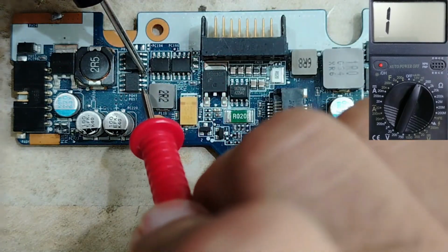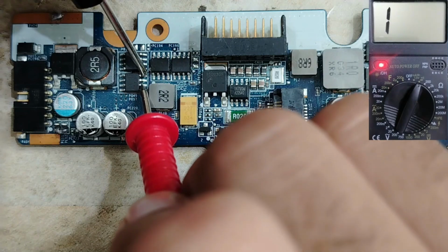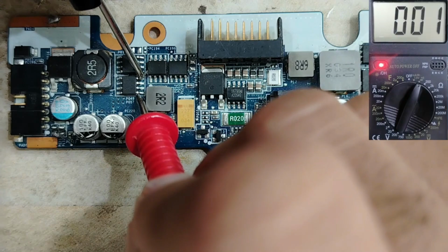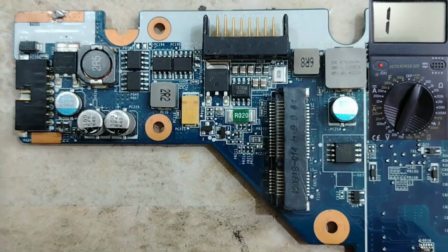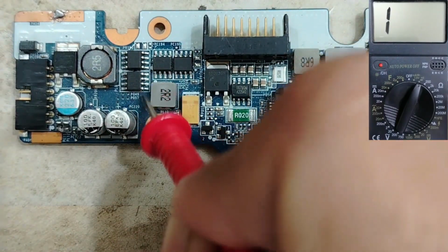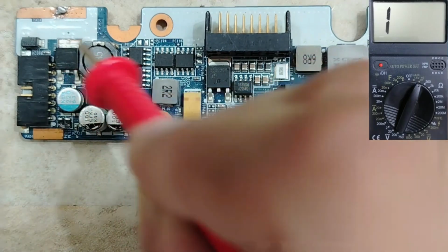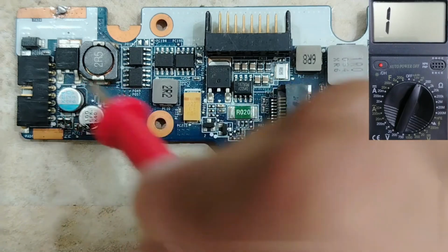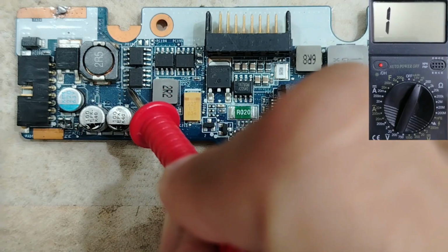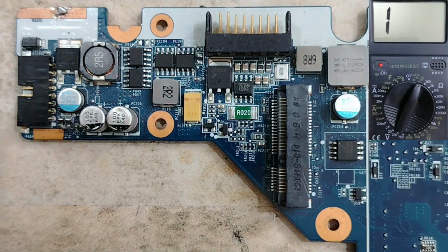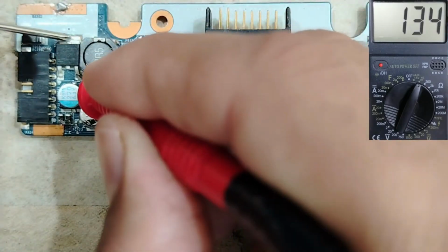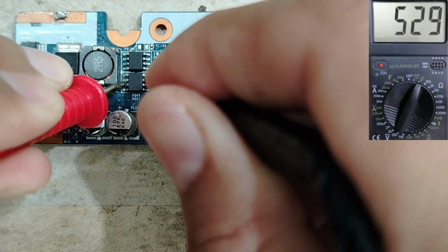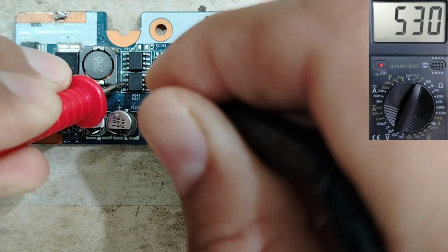Also for beginners, we can even check the continuity. All these pins are connected together, as you can see. All those pins are connected together. So all these 4 pins are just like the drain, and these 3 pins are like the source over here, and this is the gate. To check this kind of MOSFET is easy, exactly like this MOSFET, as you can see. We can just check between drain and source. We get a reading, means this is a good MOSFET.